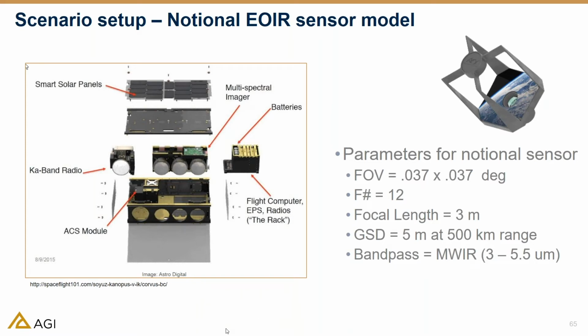And so what we'd have to do first and foremost is get a much better payload. So what we'd have to do is swap out the sensor model first of all. There's a broad-based multi-spectral sensor, and then we have to put in a new high-resolution thermal sensor, and we'd probably also have to give it a deployable aperture to help increase the focal length to detect a target like this.